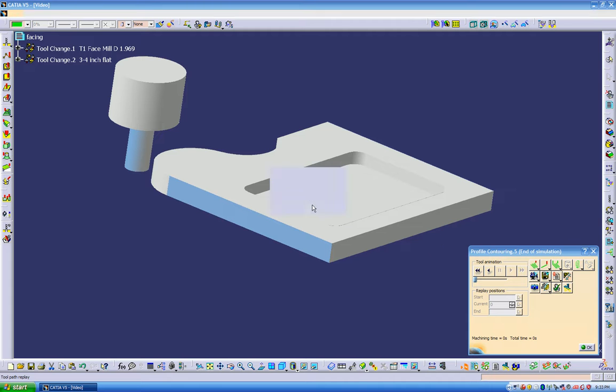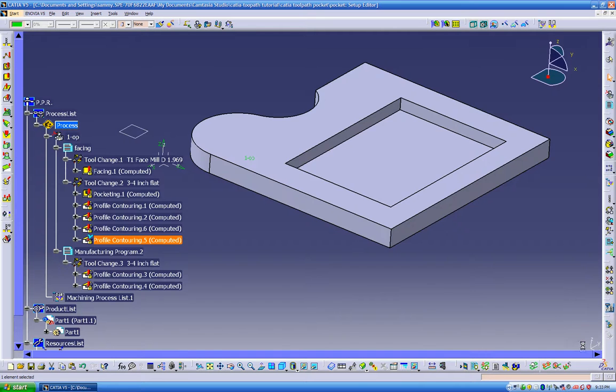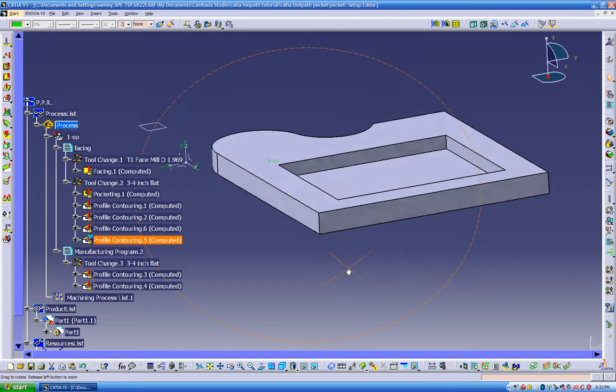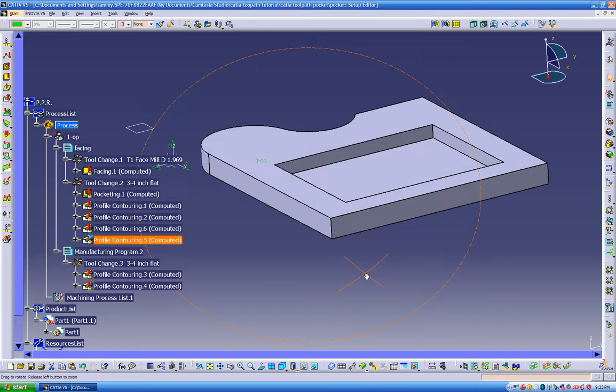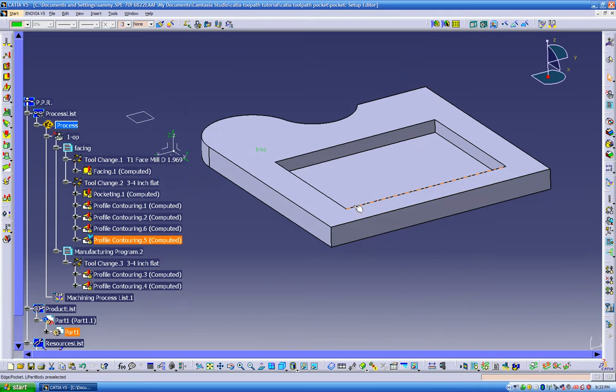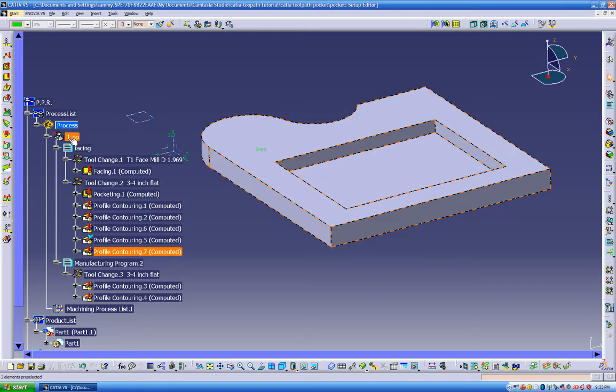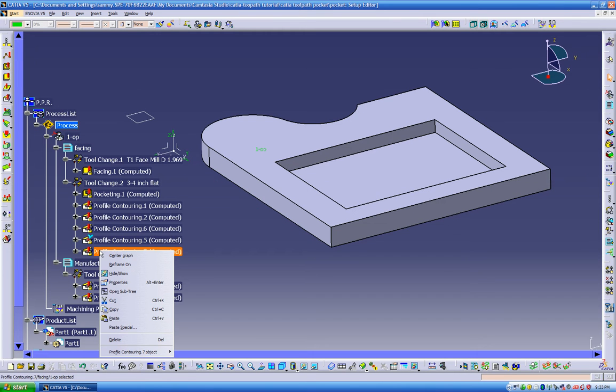And we can save it again. Okay, and that's one way of machining the profile. But for example, if this part has got some holes in here, we can screw the part down through those holes, and we can walk around the part in one shot. So let me copy this one more time, and I'm gonna paste it under this same manufacturing program. I'm gonna unlock it.